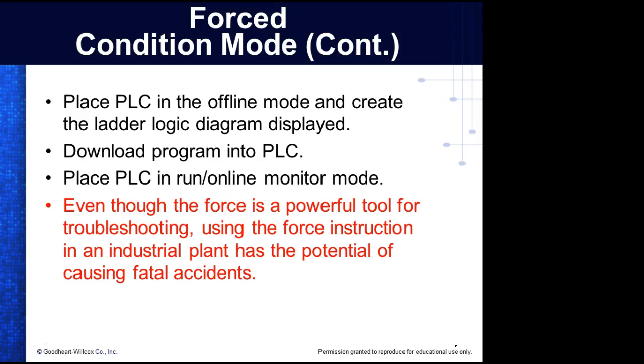Even though the force is a powerful troubleshooting tool, using the force instruction in an industrial plant has the potential of causing fatal accidents. And I should add some more tearing of the equipment. You could bring big clamps down on something and squash it, and you can swing something around and wipe stuff out with it. I think I told you about me forcing a relay and bringing down a side clamp, right? Did I tell you that story? Luckily, the strip they were running that day was too small and the clamp didn't grab the strip. But